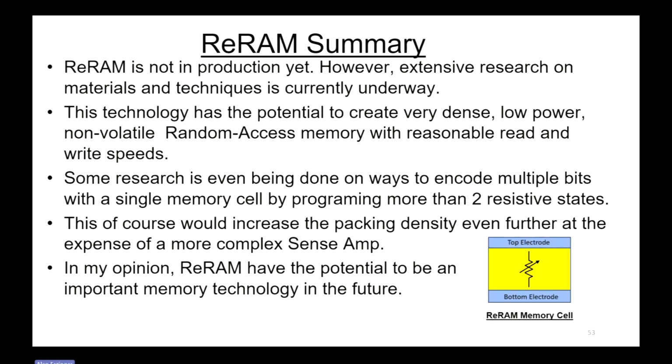Some research is even being done on ways to encode multiple bits into a single memory cell by programming different resistor values. This, of course, would increase the packing density even further at the expense of a more complex sense amp. Instead of a 1 and 0, now you have a 00, a 01, a 10, and a 11. So in my opinion, ReRAM has the potential to be an important memory technology in the future, but it's still really under development.